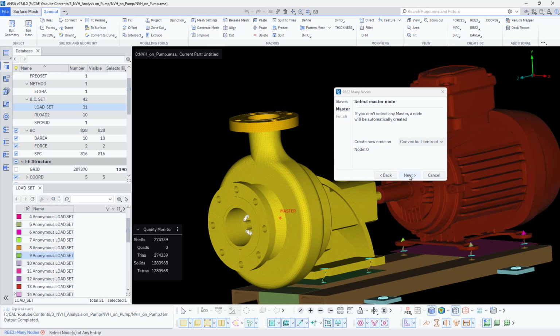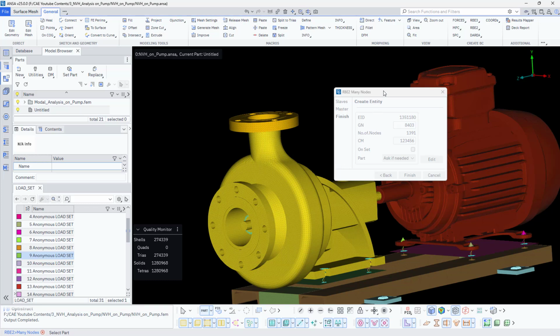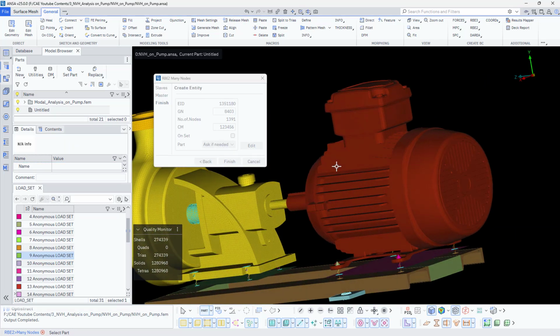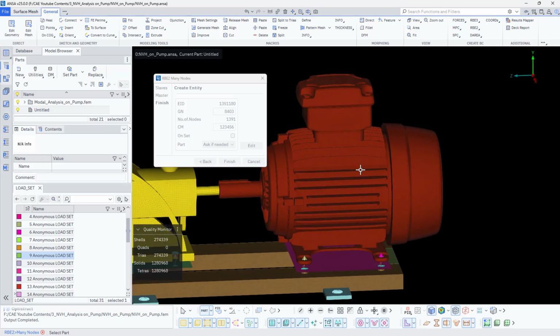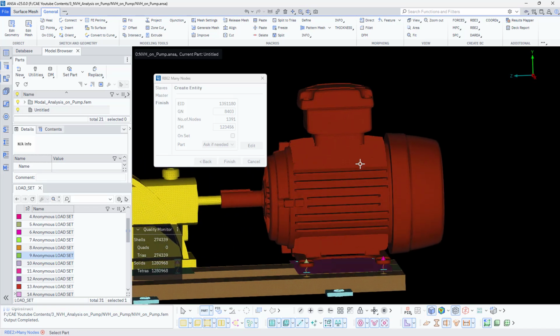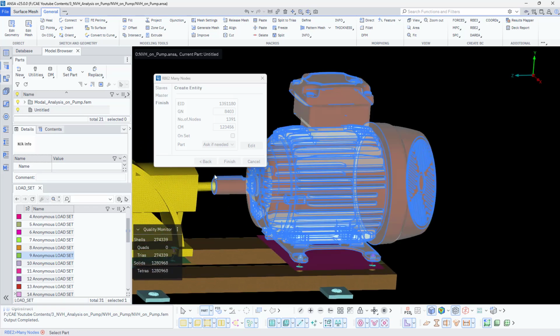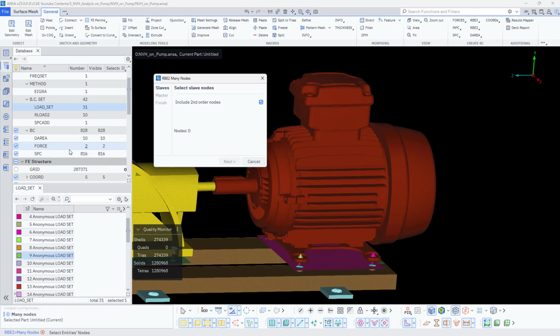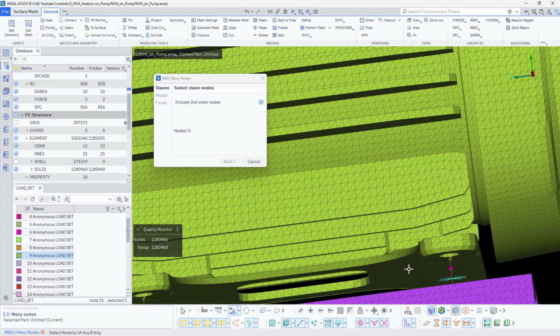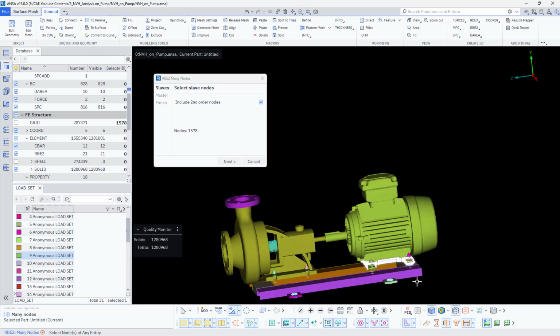Anyway, it will be distributed for this whole model, as the analysis is just an approximation, so I'm just doing it roughly as it is self weight. Practically, if you think so, I should consider the whole model, and then I need to consider the load impact, correct? So here I'll just select this face as a reference, middle click.